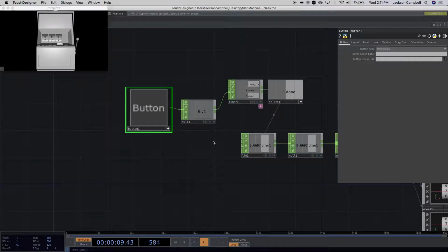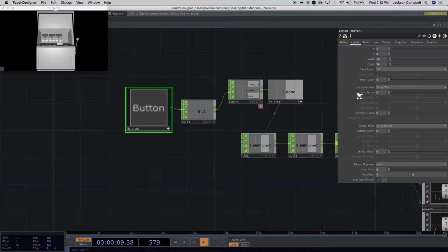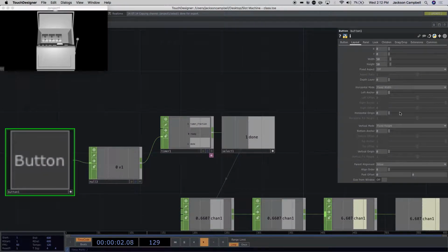There are a couple of ways you can execute Python commands. You can do it with Python code in the parameter window, where you're creating some sort of relative reference between 2 objects, and as one object's value changes, it's changing the other object's parameter, and maybe you've added some math to that, like multiplying by 36 degrees and adding 72, like we've done.